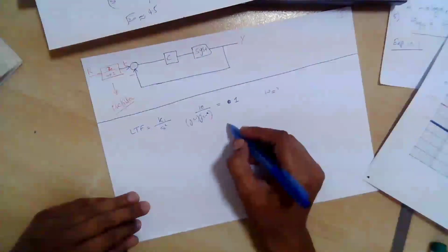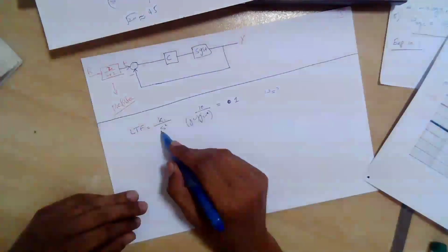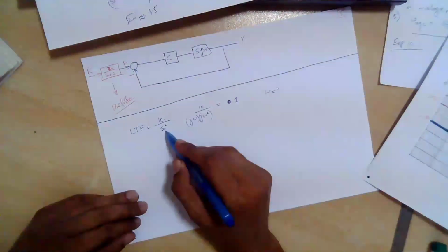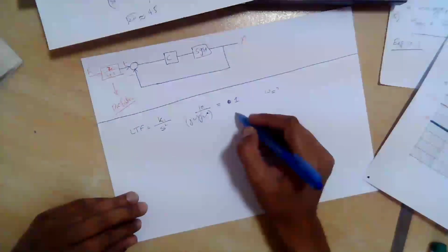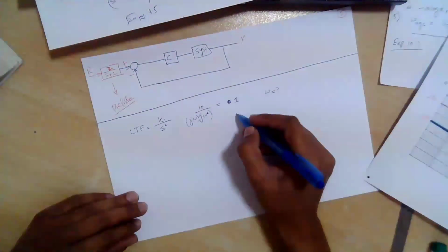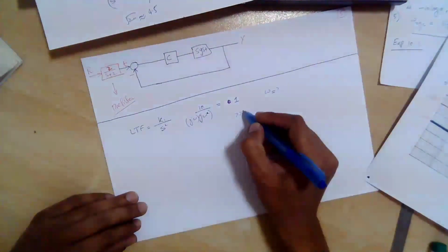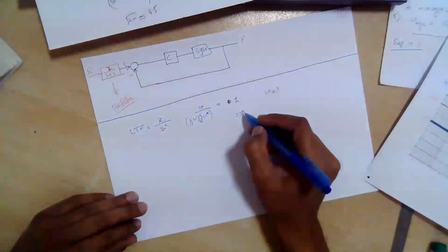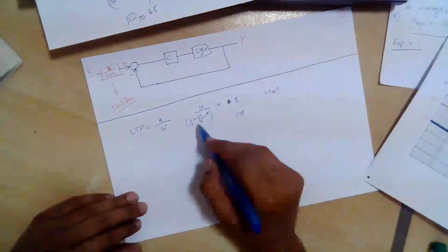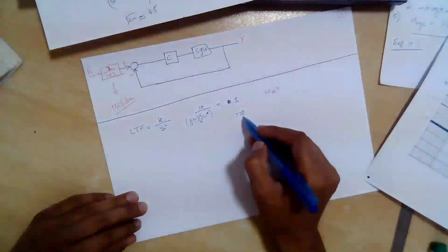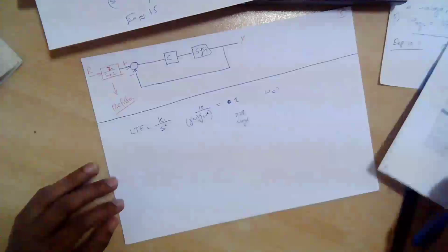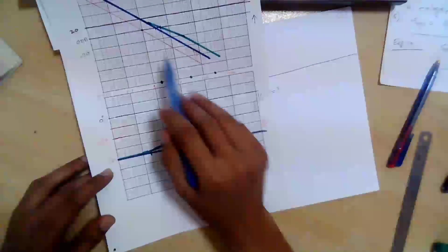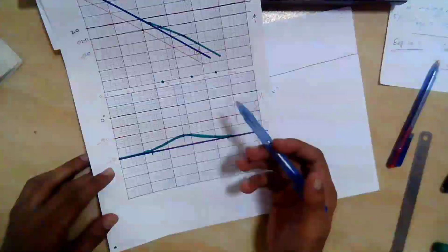And phase, we already know that is 180, right? And using the same formulation, I can calculate omega is equal to 10 log alpha, which was 7.78, and I can calculate the magnitude corresponding to this 10 log alpha. And basically, what I'm trying to say, for this type of simple problem, we don't need to plot these Bodes. We can do analytical calculation easily.